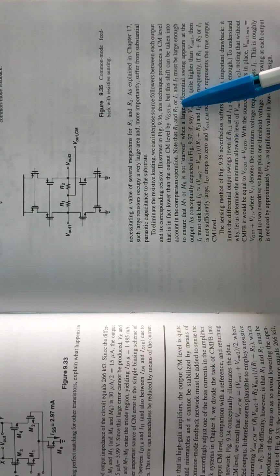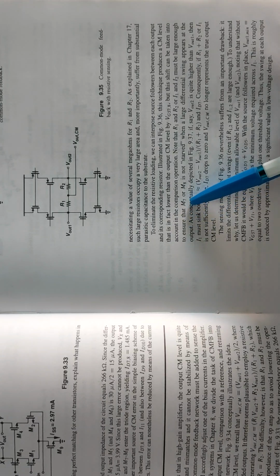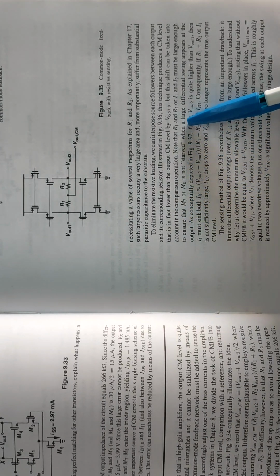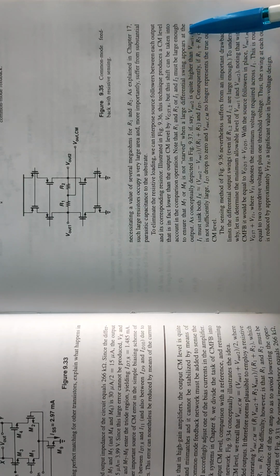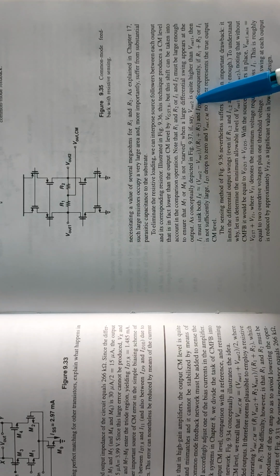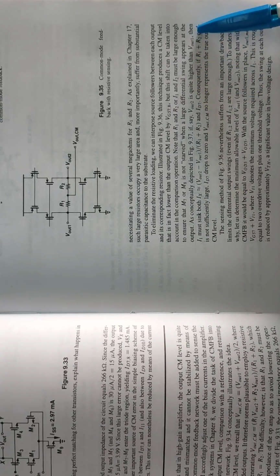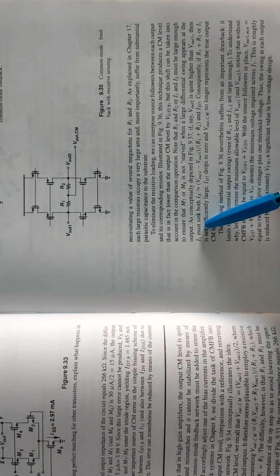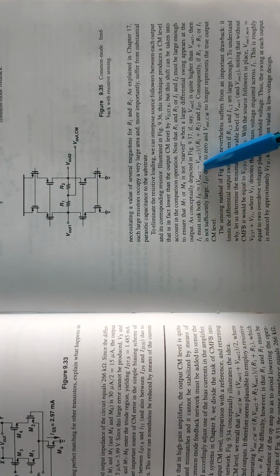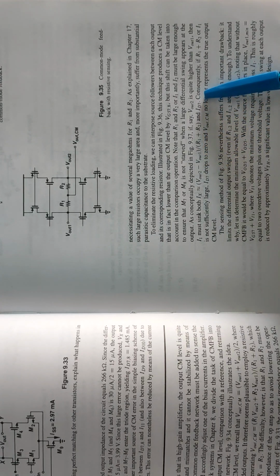Note that R1 and R2 or I1 and I2 must be large enough to ensure that M1, M7 and M8 are not starved when large differential swings appear at the output. As conceptually depicted in the figure, if say Vout2 is quite higher than Vout1, I1 must sink both Ix, similar to Vout2 minus Vout1 divided by R1 plus R2, and ID7.